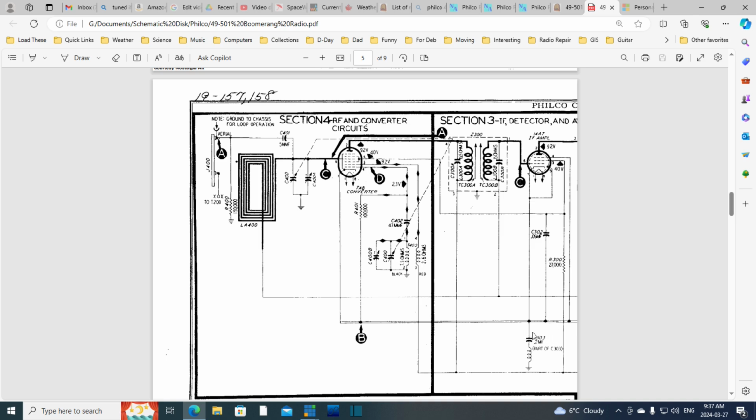So I think the problem here is, if you just use a capacitor, well, why is it even a problem? I was going to say, if you just use a capacitor, then you have some amount of reactance in the capacitor all the time, and you won't achieve this great result. Well, you can knock off the capacitance at one frequency by making a resonant circuit with a coil. You can get the capacitor out of there; a coil disappears too at the resonant frequency. And that means, well, what else is hooked to it? So this is hooked up to the chassis, this is hooked up to the chassis. Basically the antenna system. Kind of.